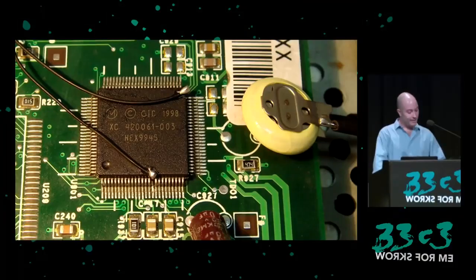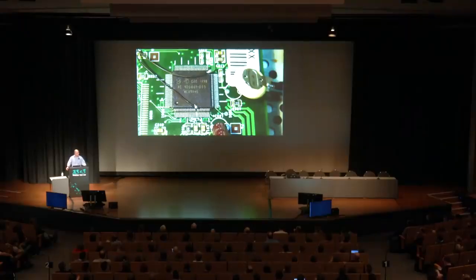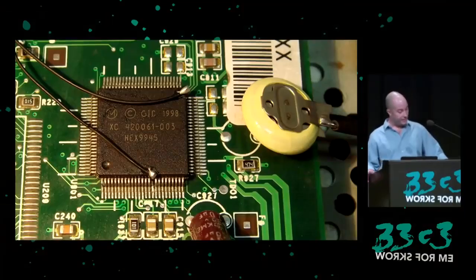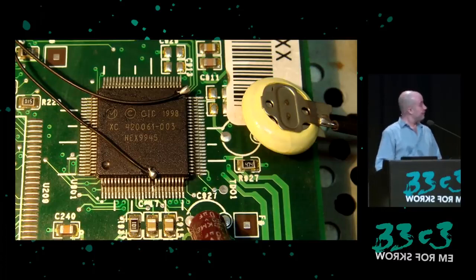With the pins lifted, an external battery can be attached. After attaching an external battery, the set-top box is unplugged and the ACP can be removed from the set-top box using hot air. The ACP can be removed from the set-top box, glitched, and can even be placed back in the set-top box if desired. To do this, I just use hot air and a lot of flux. Additionally, once the interesting keys have been extracted, it might not even be necessary to replace the ACP in the set-top box.